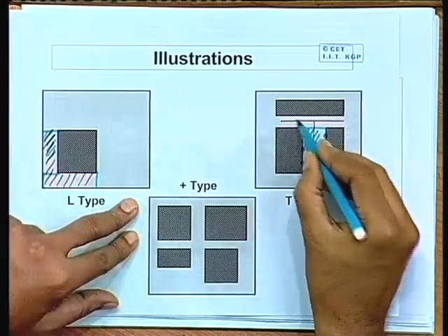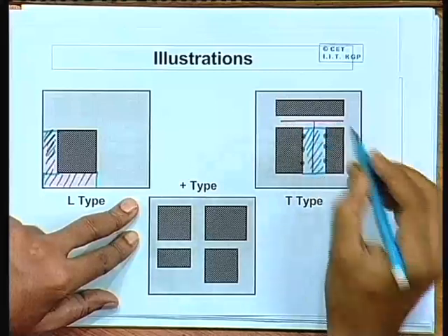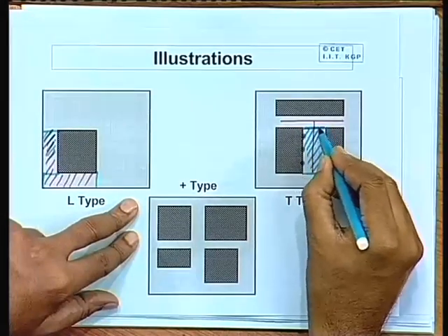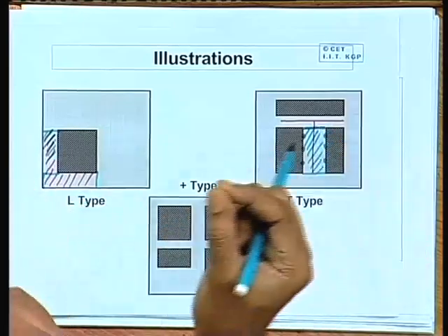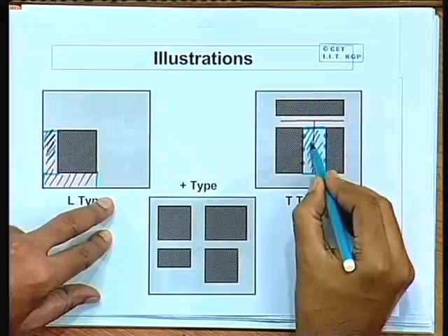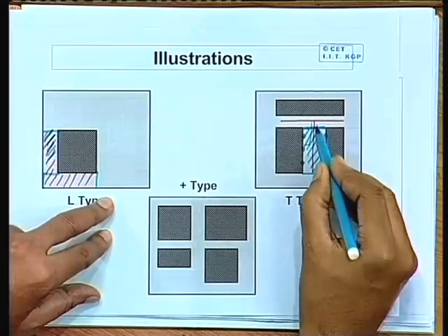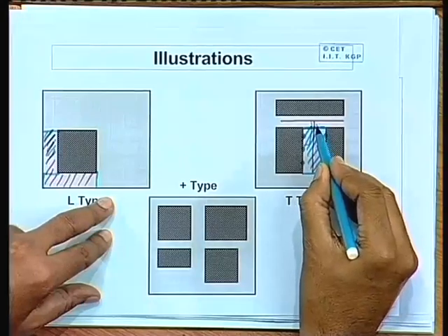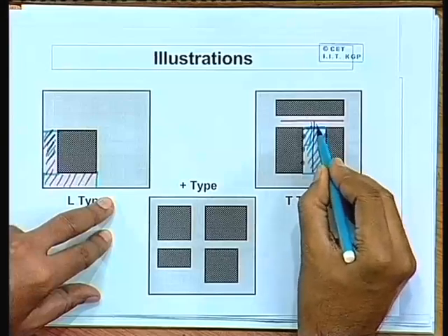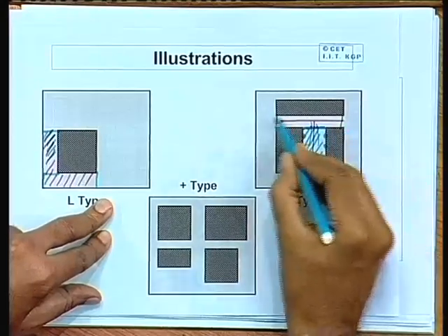Well, moreover, there can be some pins out here also, but on this boundary, the position of the pins is not fixed. Those are so called floating terminals. So, as this channel routing is completed, those nets which are going out of this will get assigned some fixed points on these boundaries. Now, after these points have been fixed, this becomes more like a conventional channel.